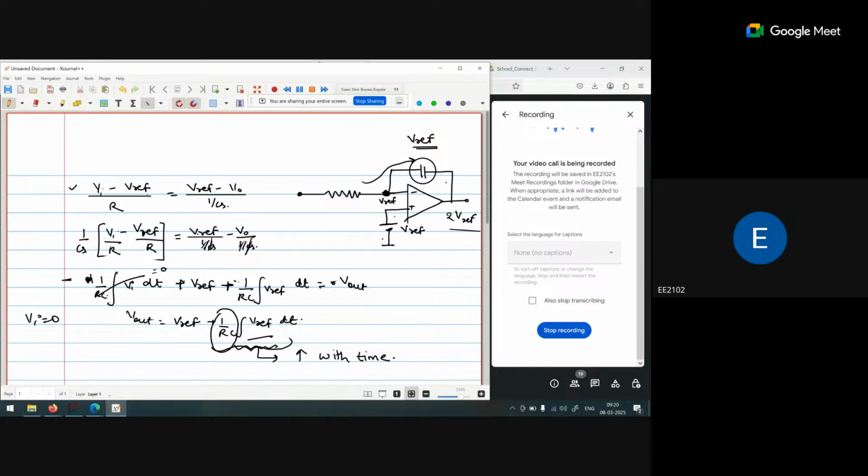So your output voltage will increase. Now how will it go, slowly, because this capacitor will charge and discharge. If I remove the V ref voltage, this capacitor will discharge across the resistor. So due to the charging and discharging, it will increase, then decrease, then again increase, then decrease, then again increase. In this way, it will slowly go toward the completely full charging, full voltage.